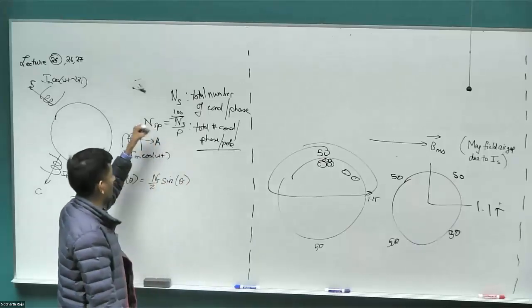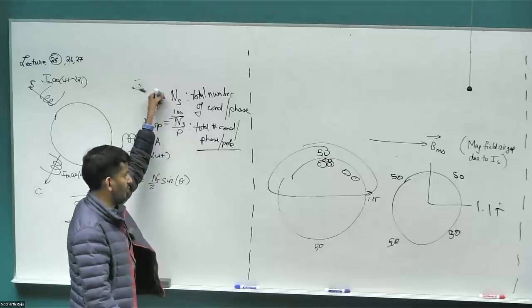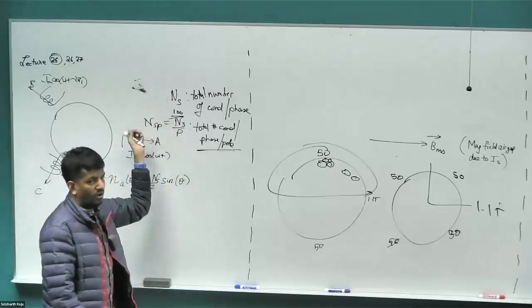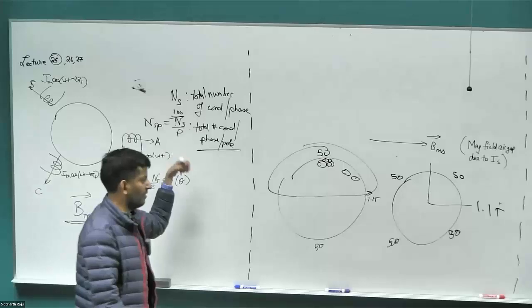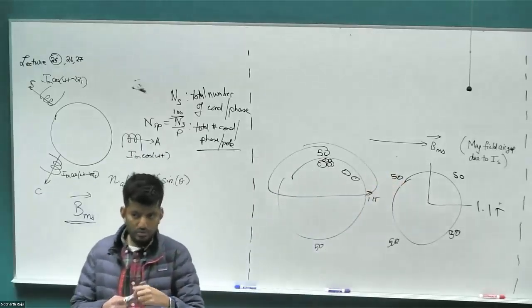As people who are trying to understand how a motor works, NS is a useful term, but a machine designer would usually talk about NSP. If that is constant, then the torque can be increased if you increase the pole count. Okay. Any other questions?